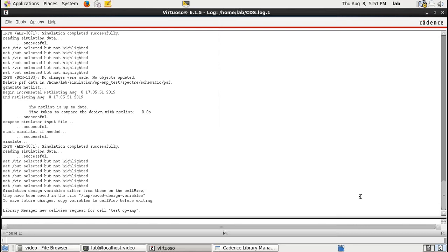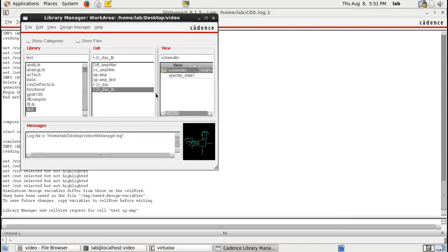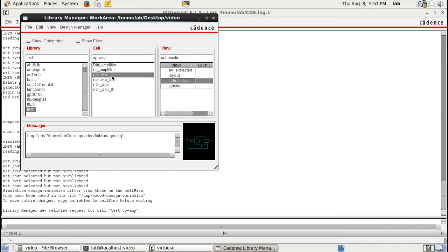Hello everyone. So now let us look at the working and the simulation of an op-amp, following which we will try to build the layout for an op-amp. So in general, when you're building an op-amp, the blocks required are the differential amplifier and common source amplifier. So we have to remember that before we can commence the build for an op-amp, we require the designs of both the common source amplifier as well as the differential amplifier.